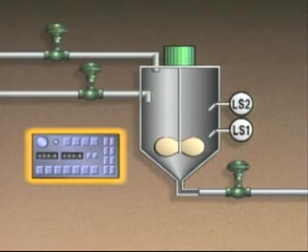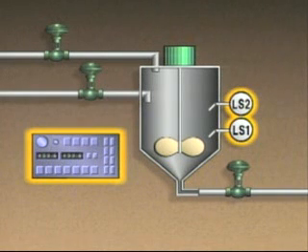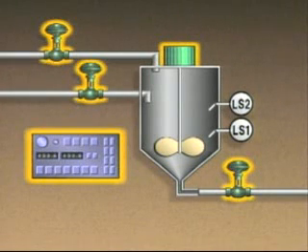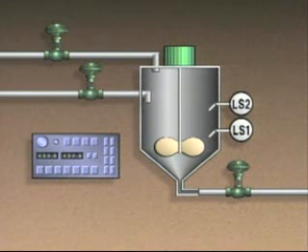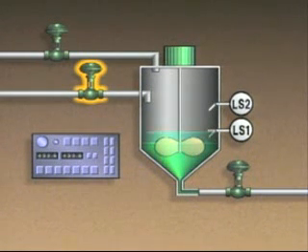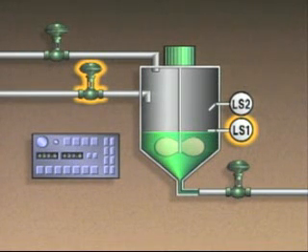During operation, the programmable controller reads input signals from these two level switches. Then it evaluates its control logic program and sends signals to the valves and the agitator motor. To begin, the programmable controller opens the lower inlet valve to start the flow of the first fluid into the mixing tank. When the level of the fluid reaches the lower level switch, LS1, that switch is energized.